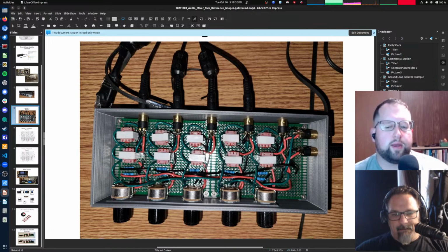Yeah, I appreciate that. Just to really double check myself, as far as those transformers, I should see continuity between the left channel and ground on the input side of that transformer, and then continuity on left channel and ground on the output side, right?